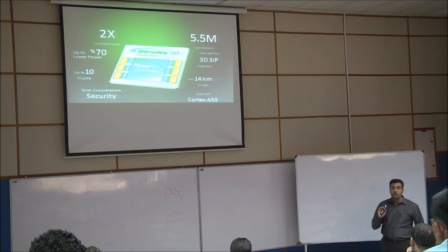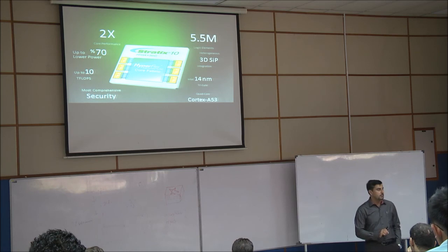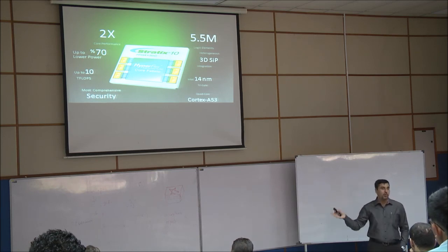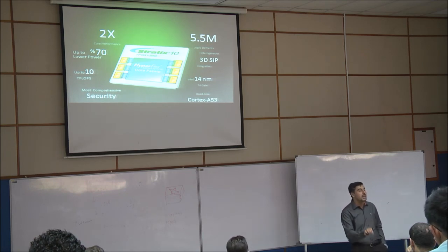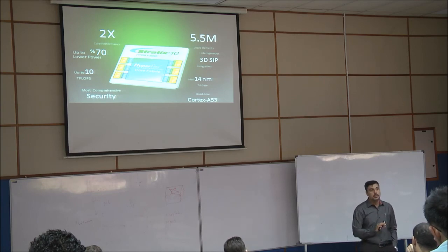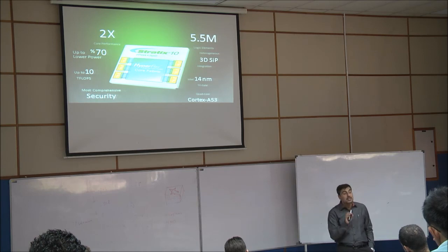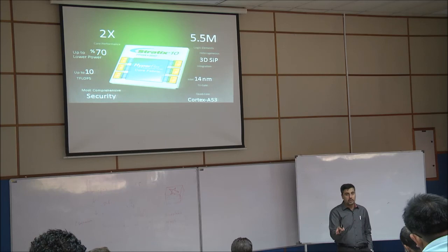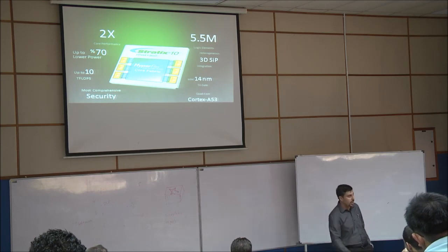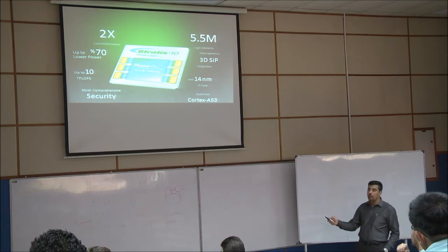Security, yes. Working in Word, they can hack your design, so this is more secure. Before, also in CPLD and in some FPGA, and currently also, we can lock our design inside the chip. Because if your design is inside the chip, there is a possibility to read your design from the chip. If we read your file, we can still copy your design. So to protect this, they put a password, a protection, so your design will be protected. Nobody can take it. You make it near to impossible for them to hack your design. So it's more secure.